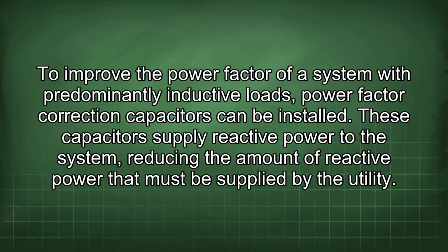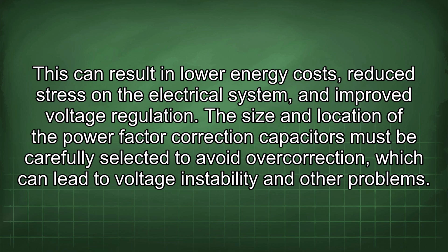To improve the power factor of a system with predominantly inductive loads, power factor correction capacitors can be installed. These capacitors supply reactive power to the system, reducing the amount of reactive power that must be supplied by the utility. This can result in lower energy costs, reduce stress on the electrical system, and improve voltage regulation.